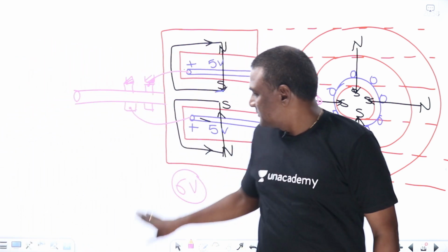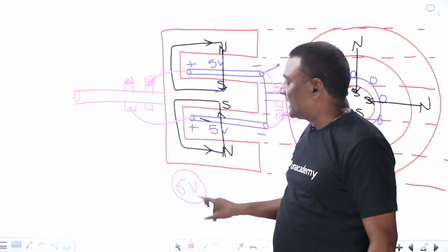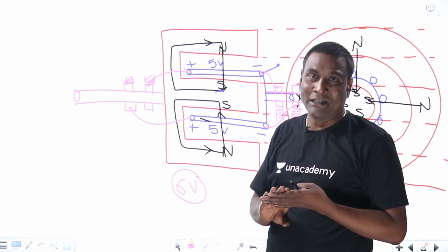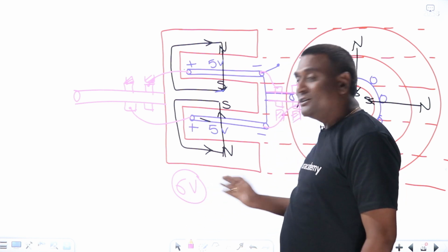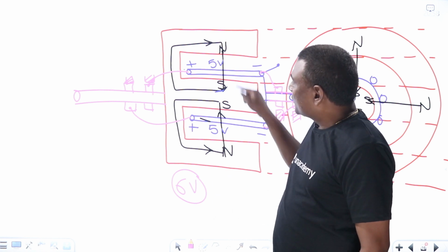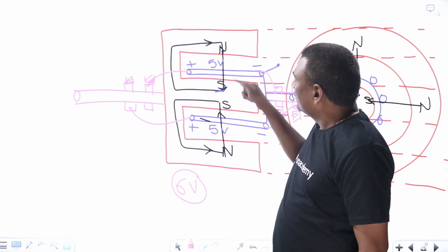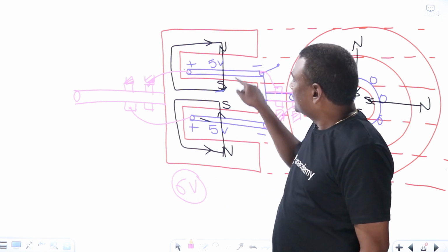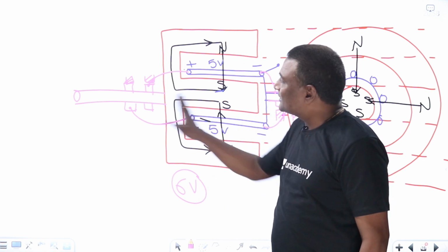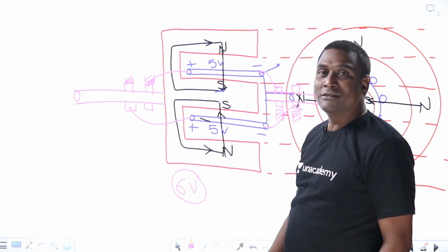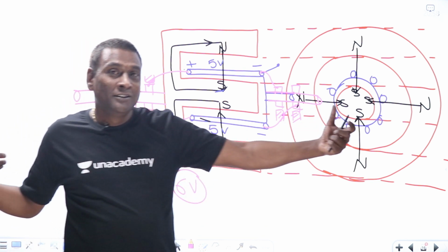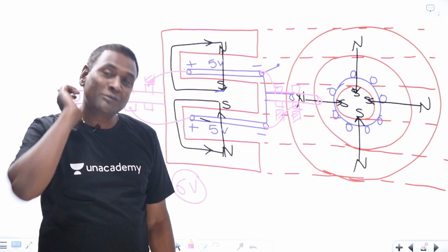Now, with 2 conductors, I have 6 volts. For 2 conductors, I need to maintain 4 slip rings and brush contacts. For example, if I want to maintain this at 600 volts, then for 2 conductors I am able to get 6, so I need to have 200 conductors. For 2 conductors, I got 4, so for 200 conductors, I need to have 400 slip rings and brush contacts.